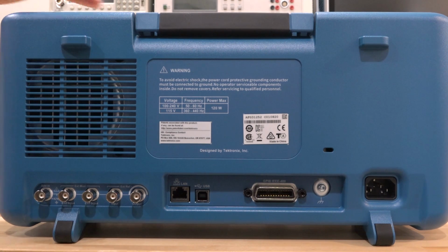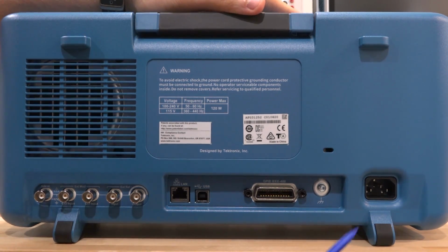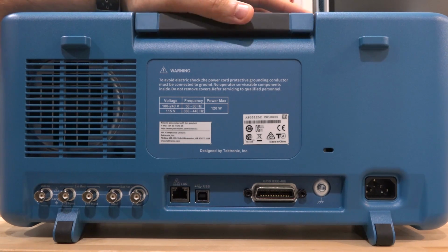And here's the back of the unit. As you can see, nothing unusual going on. We have the AC line input, of course, GPIB, USB and Ethernet are all standard as far as I know, and we have the external reference input and output, so obviously you can cascade things and give it a 10 megahertz reference so that it's perfectly aligned to another instrument. This is important, especially when you are syncing multiple of these.